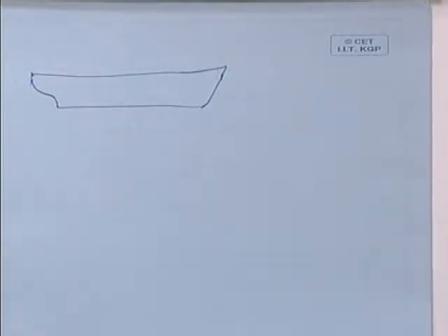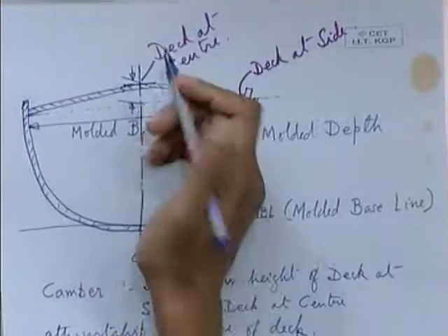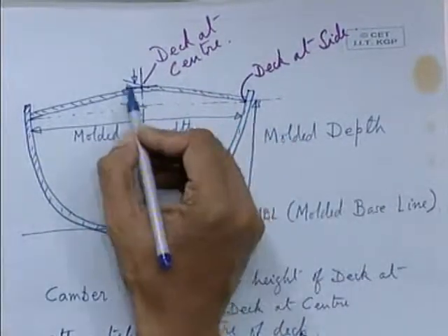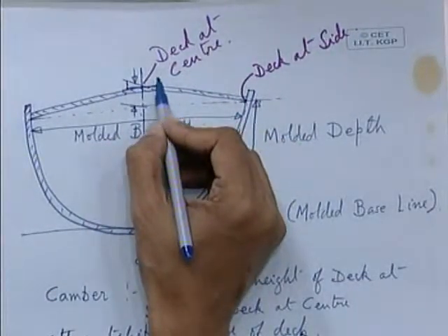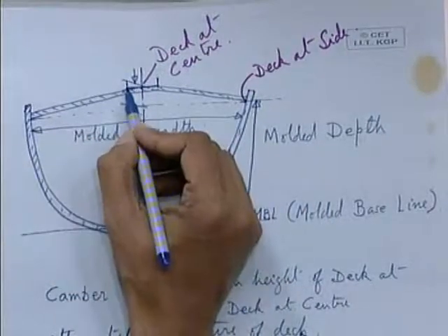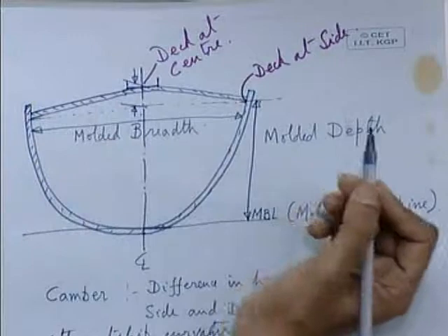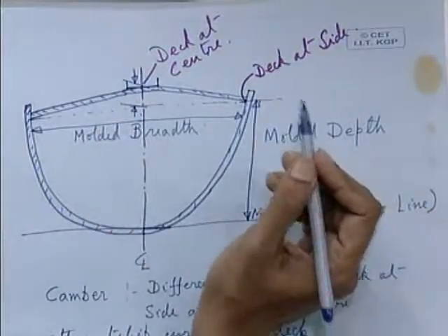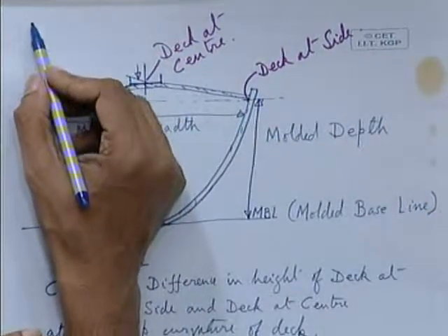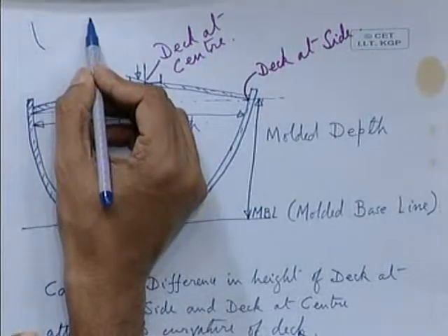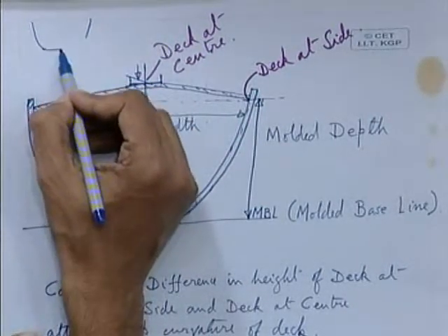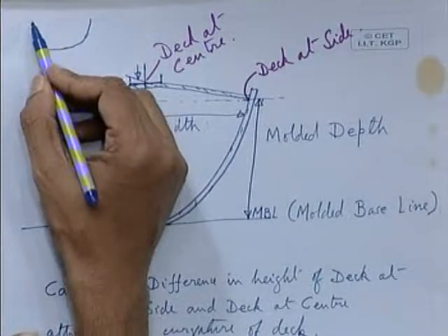In camber, here I have drawn what is a straight line camber. You can see that there is a flat region at the center line, and then there is a straight portion coming down from the center line. So, this is a straight line camber. Normally you will find in olden ships are given a sort of a curvature or a curved camber like this.